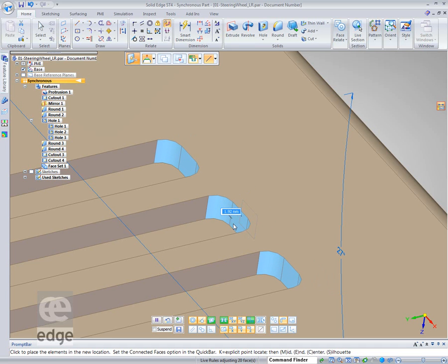As I'm moving this, we'll notice up on the right hand side of the screen there's a glyph with 1, 2, 3 in it, which is saying there's a dimension changing somewhere. Down on the bottom here we can see that live rules is adjusting 20 faces. But how can I tell which faces are being adjusted? What I'm going to do is pause.